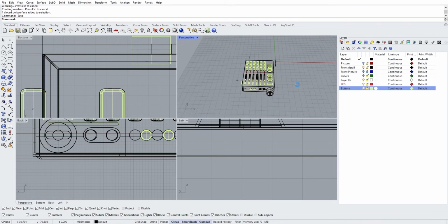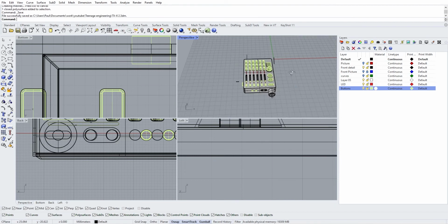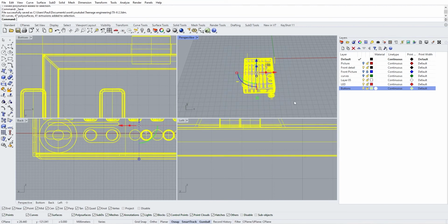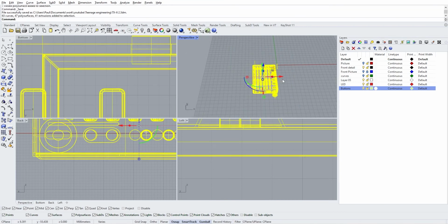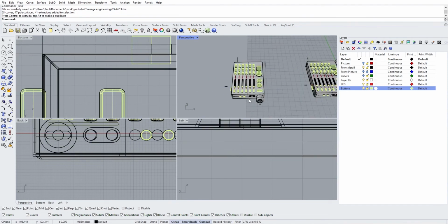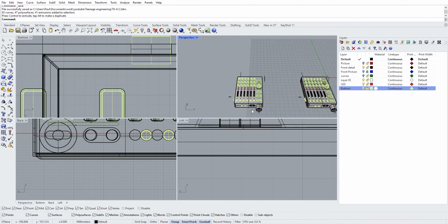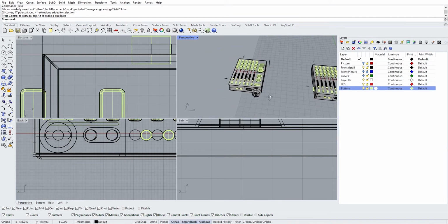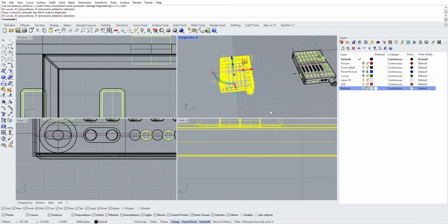So I would strongly advise you to, first of all, save regularly, but also when you start filleting, before doing all the filleting thing, you can select everything and duplicate it by using the Alt button, and so you duplicate it like this, and here you put all of this into another layer.